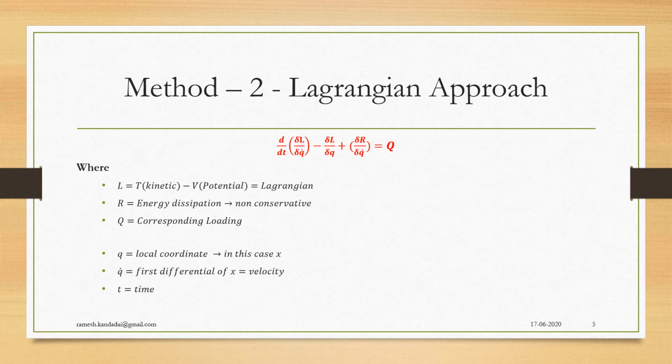There are two other factors besides the energies caused by the motion. They are the dissipation of energy due to things like friction, drag, viscous damping, etc. And of course, the corresponding external loading, which always has to be provided for from outside the system of bodies. In general, the equation often reduces, in the ideal circumstances, to a system of equations where there is no energy dissipation.